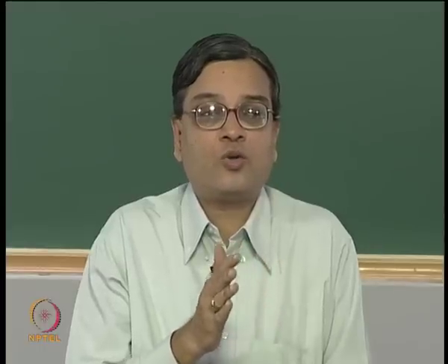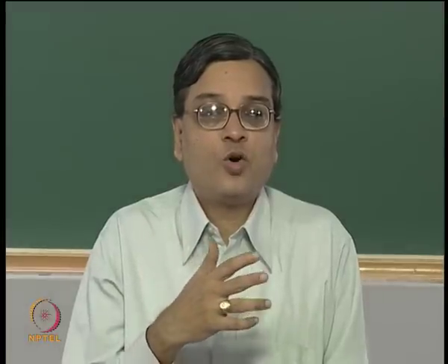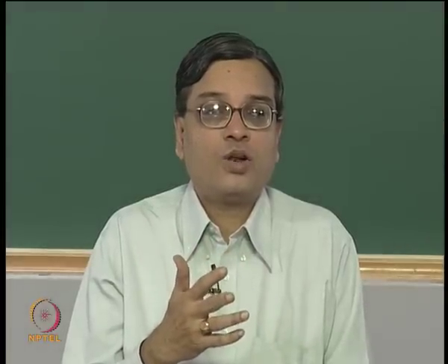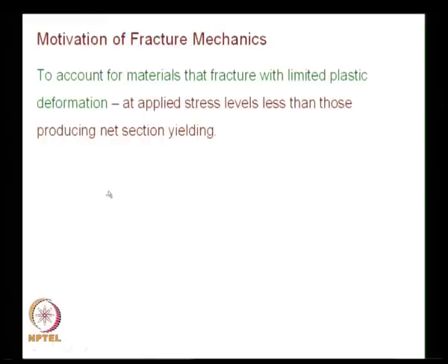Later on it was extended by Irwin and Orowan for handling ductile materials, and when you go and look at that, what you will have to learn is we also want to look at materials that fracture with limited plastic deformation at applied stress levels less than those producing net section yielding.